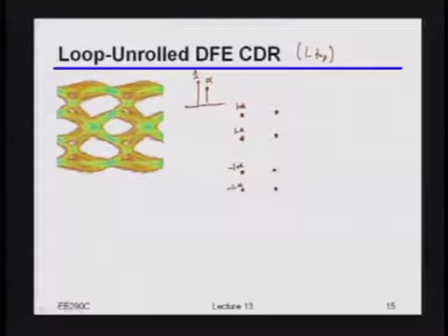The thing that's sometimes initially confusing to people is that this alpha, whether it's a plus or a minus, is correlated with what the value of the previous bit was. So you can't just draw lines from each of these possible points to each of the other possible points, because not all of those are real possible things to happen.